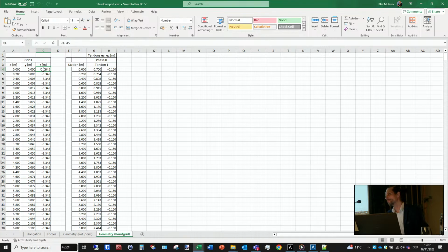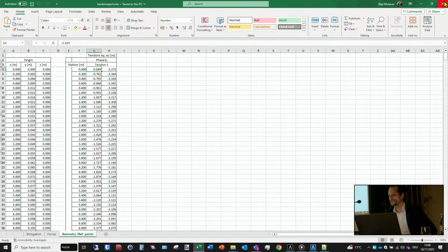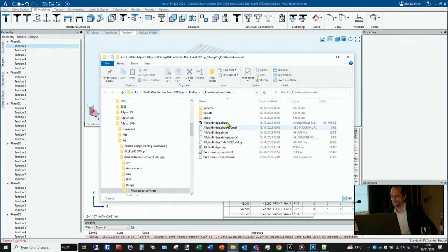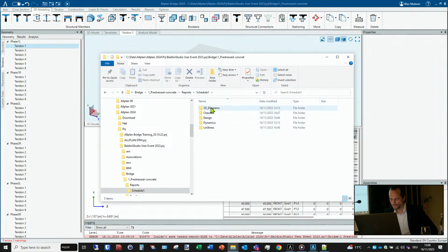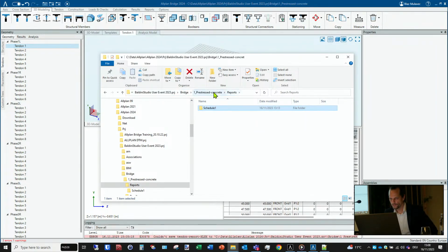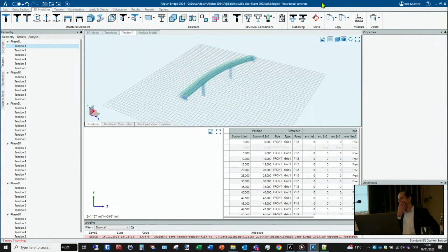And these tables, this data, is this in an Excel sheet? Yeah, this is exported. Is this table also inside Allplan, so that it is live, or do you need to always export? And put it back to the drawing. If you want the Excel data to be represented in Allplan, you can import it as an external reference. So every time Excel changes, the report is also changed, but it's not connected like the drawing. It's not inside Allplan, this table.